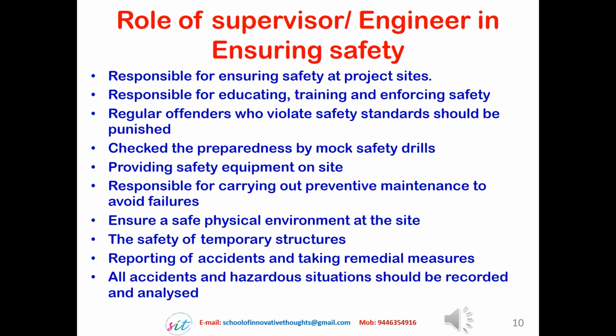The safety of temporary structures should be checked and inspected by the supervisor or the engineer before they are put into use. Many a time, accidents go unreported, so it is not fair. Any untoward incident happening at a project site should be reported and properly documented so that remedial measures can be taken to prevent such events in the future.